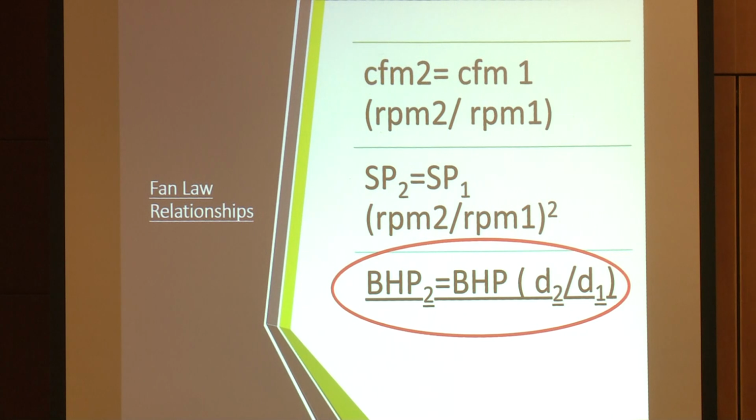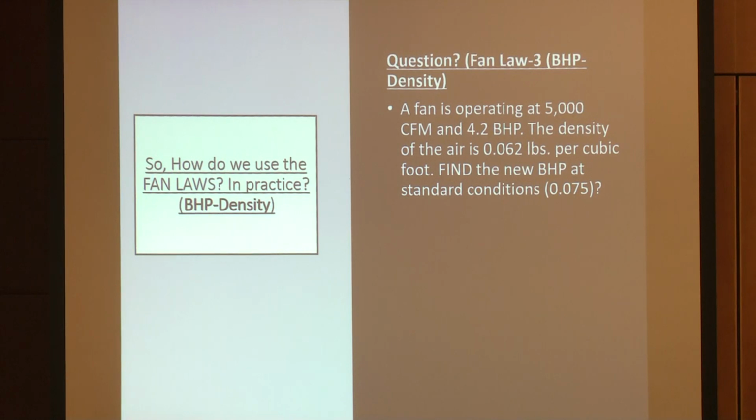But then when you graduate to pressures, your pressures end up being squares, right? So you're squaring that relationship between speed and CFM. And when you get to brake horsepower, you're cubing those relationships. I'll show you that as we go along, but that's basically how we make calculations as we go from one parameter to the next.